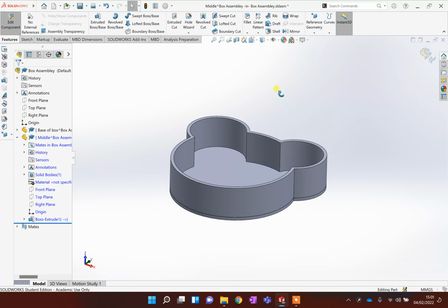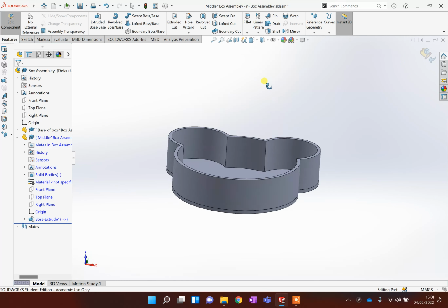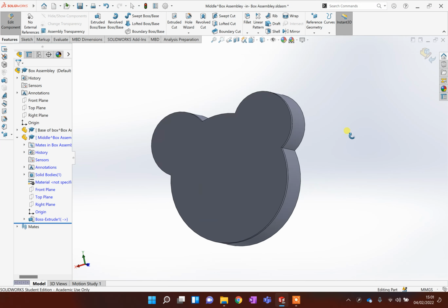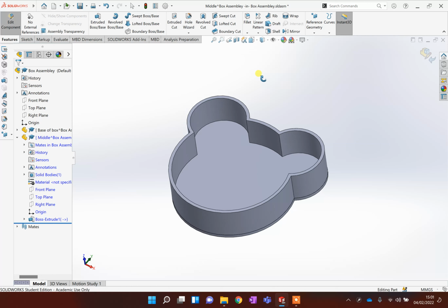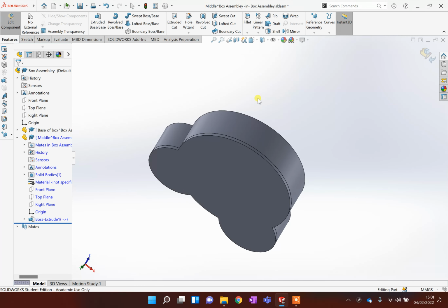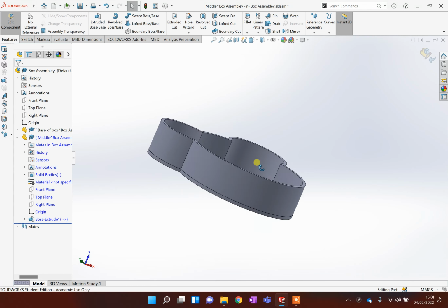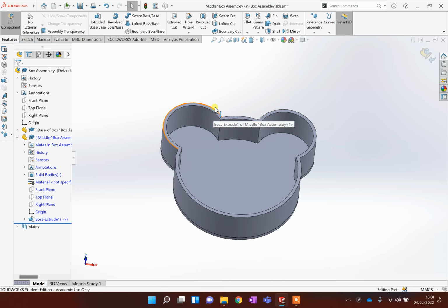Now we're not done here yet with our base. The way I'm going to build my Mickey and the Mouse box is I am going to permanently glue this bottom base onto here. However, I want my top to screw on and off with some screws so that it's removable and that I can gain access. So I'm going to add in some little tunnels. Now, whatever design box you've done, if you follow the same method for making the tunnels that I'm about to show you, they'll guarantee fit.